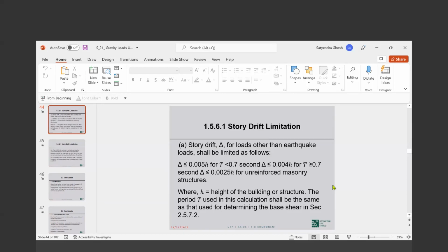Is it permitted to assign partition wall loads as uniform pressure loads instead of line loads? That's what I was trying to point out; I apparently wasn't very successful. So movable partition load, I have never seen anybody doing line loads with them.